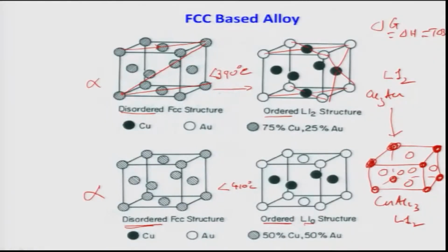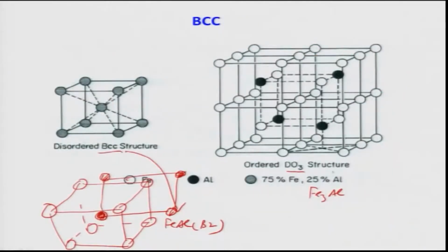The one I was talking about is basically the B2 structure. For the B2 structure, the body diagonal is this one, and this is the 110 plane. So along the 110 plane, if I displace one atom from here to there, it becomes a/2 [111] or [1 bar 1 1].